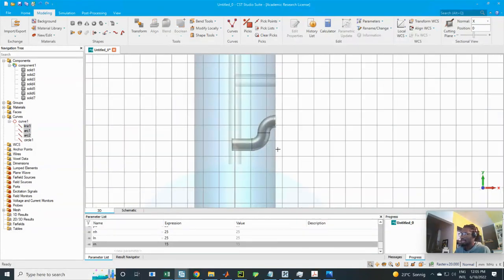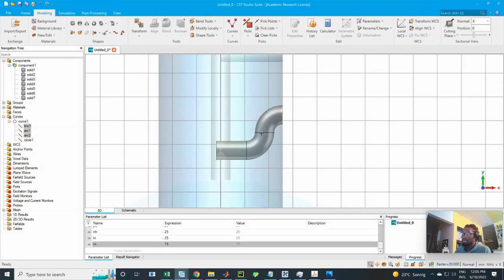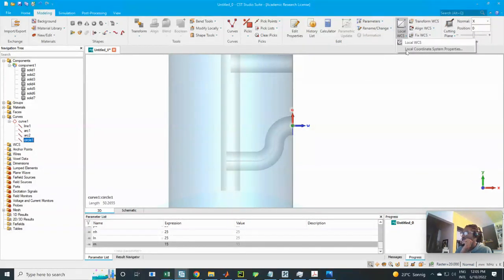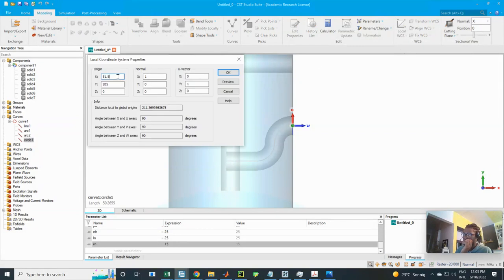Okay, so I made a lot of changes to the geometry, which is kind of important, but I won't really show it here. Basically, to make this parametric, I modified some things, and one thing I also observed was that in defining the circle's local coordinates, the parameters here were not updated, so I had to update it and move the circle again.